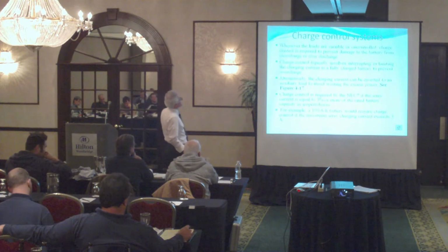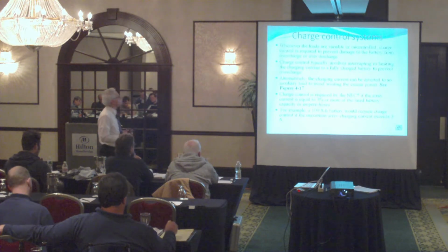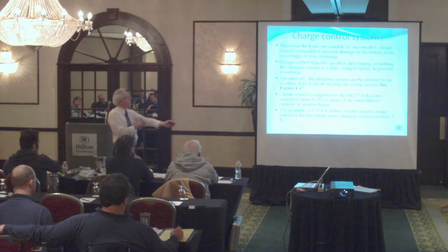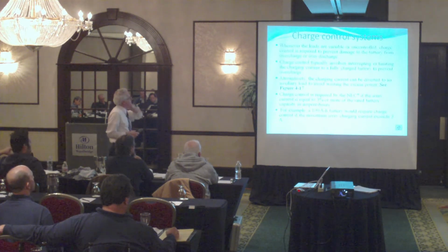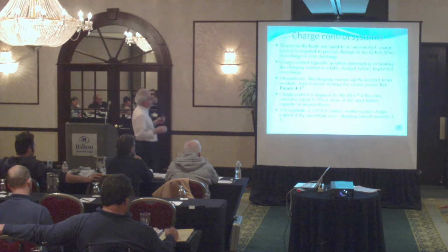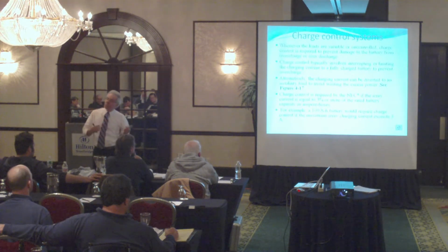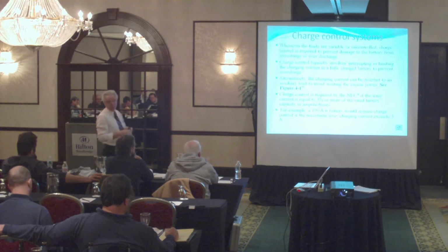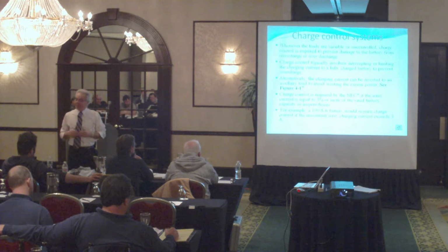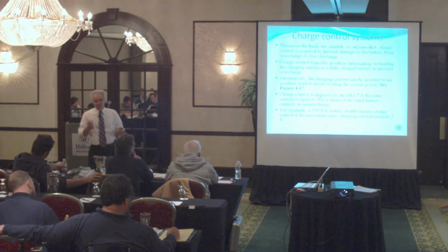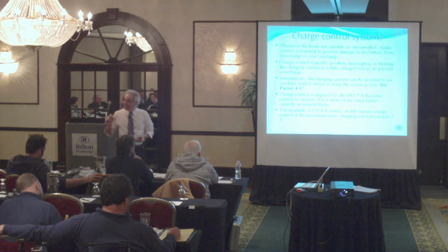Charge control systems, the types you have. You put in systems that actually prevent the battery from being overcharged. You provide some sort of method to limit the charge current to a fully charged battery, to prevent overcharging. Or sometimes, in a standalone system where you're generating more, you switch an auxiliary load on, so that the extra power can go there.